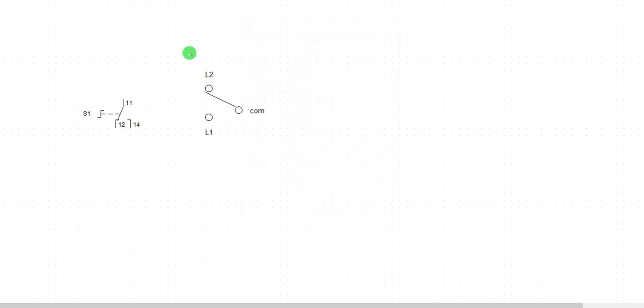Okay, this switch one. I want to use this one to represent that same configuration because this is two terminals. Terminal 14, terminal 12, and terminal 11. 11 is my common. Common is now connected to 12. So in a control language, we call it NC/NO, normally closed, normally open. This one is common, closing to 12. So this 12 now is normally closed. Then 14 is normally open.